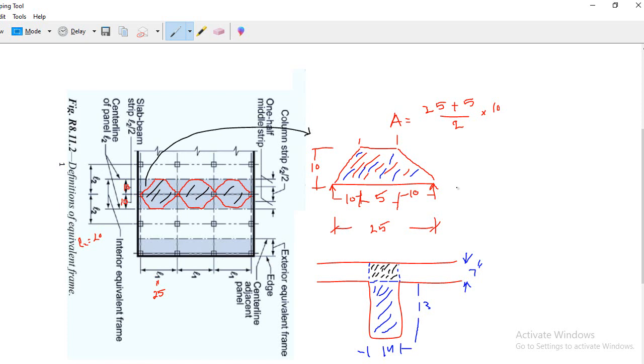We show the tributary, the trapezoidal loading, and then we convert that loading. This is the tributary area. And next, finding this area. Once you find this area, that is 150 square feet roundabout, clear? Now you just multiply your load, that is, you find out per square feet. With this you get the total load, and if you divide this by 25, you get load per feet.